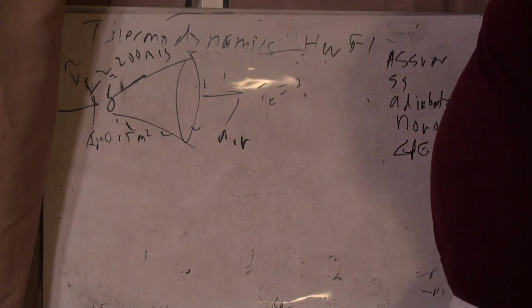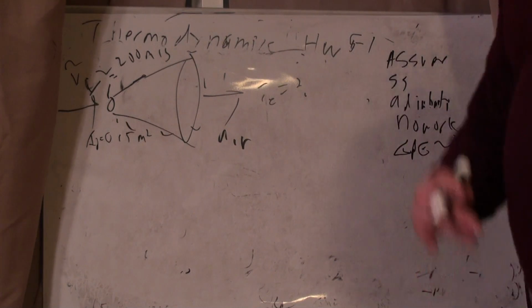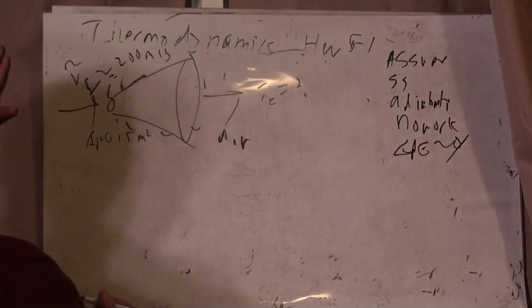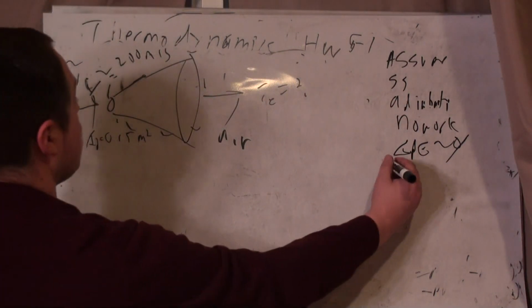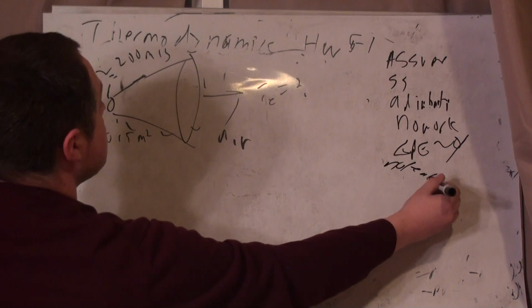and I'm also going to assume that delta PE is approximately 0, but obviously not delta KE. I'm dropping to 100 meters per second. Okay, that's pretty big. That's the whole point, that's where the energy balance really comes from, is how much kinetic energy is being transferred to enthalpy. Okay. And so I might have some other assumptions, maybe like no leaks, but for the most part that's what